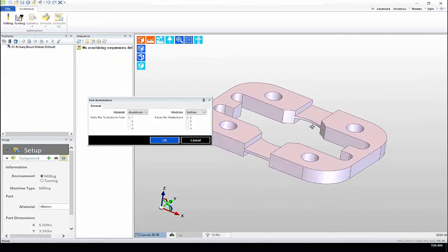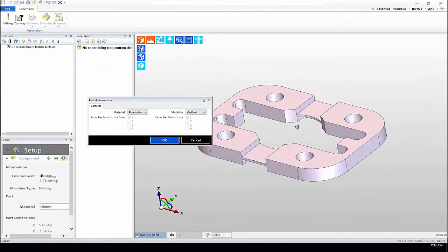The native solid model is loaded but not translated. As you can see, this is a true 3D model. The dialog shown can be customized to fit the customer's requirements. Your material can be added in order to drive the tool selection, including your own proven speeds and feeds, as well as additional options. Please note that the dynamic options based on the machine type for this session have been selected. We will focus on a 3-axis mill. However, almost any machine configuration and process can be incorporated into the system.